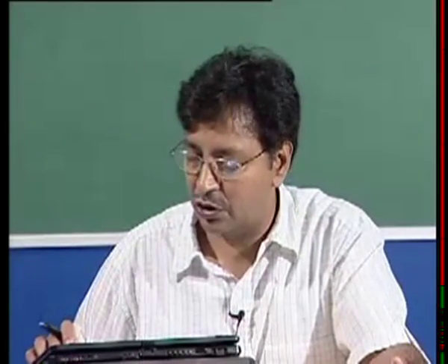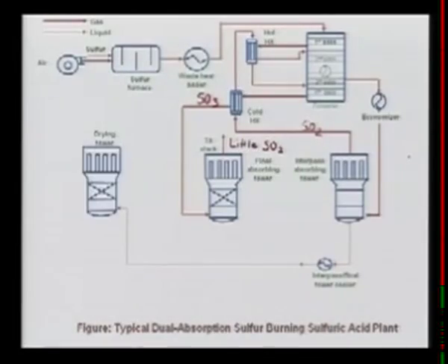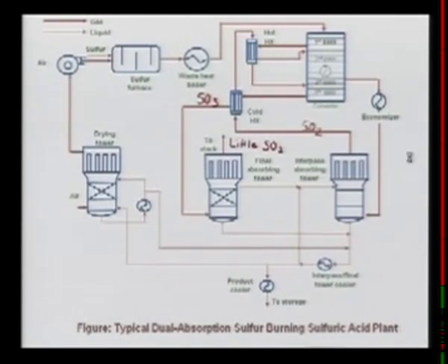So let's complete the picture here. That is similar to what we had done last time. So what we are really doing is converting the SO2 two times to SO3. First conversion route, and then whatever remaining, converting it again and absorbing it again. And then whatever little remained is sent back. So this process is called DCDA, double conversion, double absorption. But the focus for us has been how to reduce SO2 emissions.